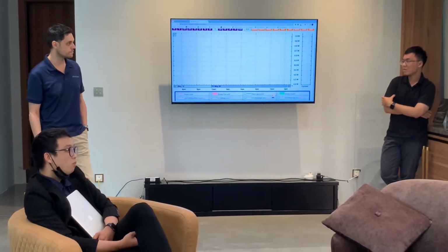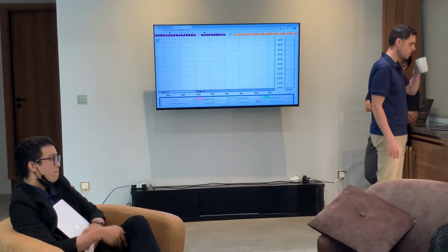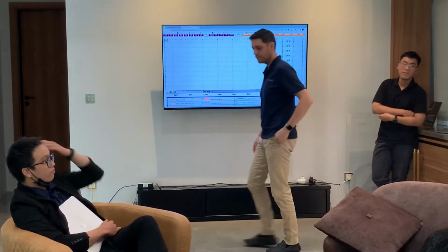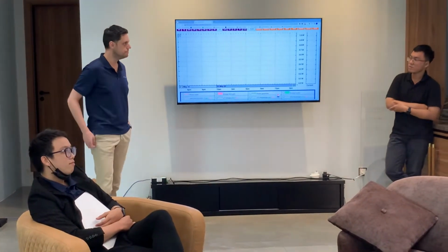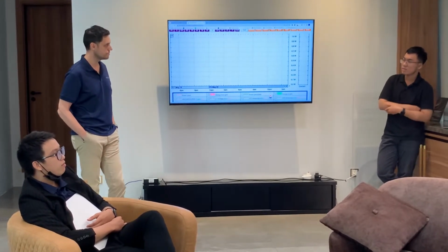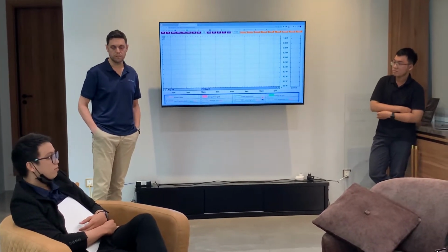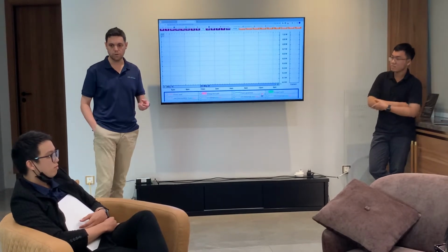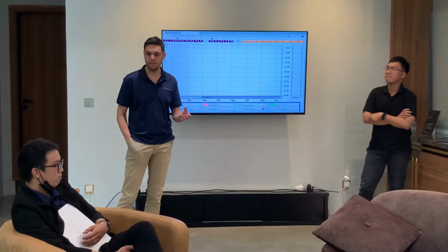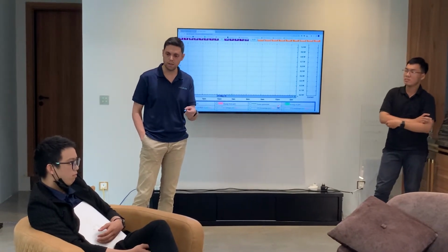So Tom, my question is about how we calculate or design a circuit. For example, we have the lighting in the house, we have the AC, and we have the speaker. Yeah. So we can divide it into 3 circuits, and we measure those 3 individually with 3 CTs. Right. There are different ways you can do it. You can measure the breaker, so anything that's plugged into that circuit, or you can measure the individual device by itself before it plugs into the wall.